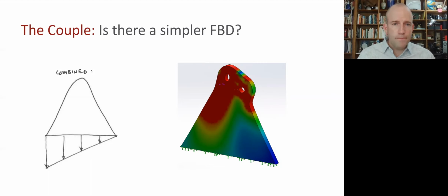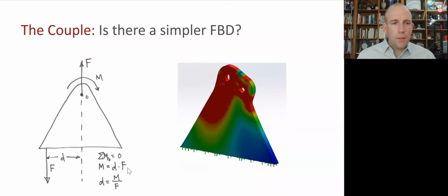So hit pause now. All right, so the trick here is to recognize that for static equilibrium purposes, you don't need to know everything about the stress distribution. It's sufficient to know what the integral is, that gives you the total force, and where the center of pressure is. And we'll get an equivalent statics result if we apply that force at the center of pressure. And so something like this is a good free body diagram for this component as well.